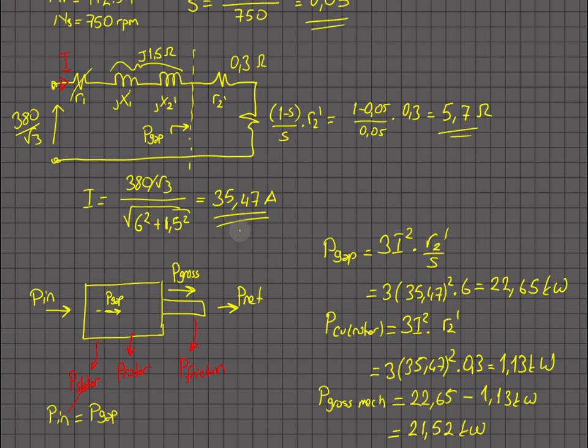Alternatively, you can use the impedance angle of those circuits, so you can calculate the value of the j omega L components and resistive components. So you can calculate the phase of I, it will be lagging. Then by the power factor, you can multiply 3 times that voltage times current, and you can get the real power. But don't start your input power calculations by directly multiplying these two.